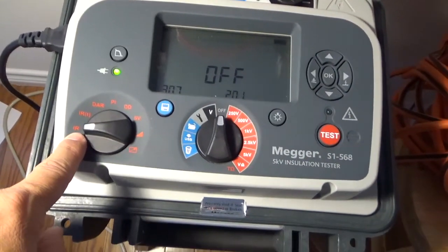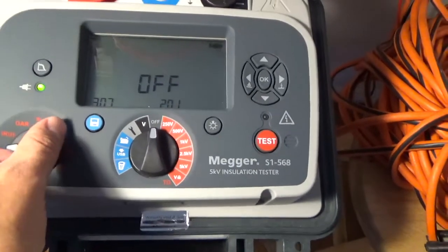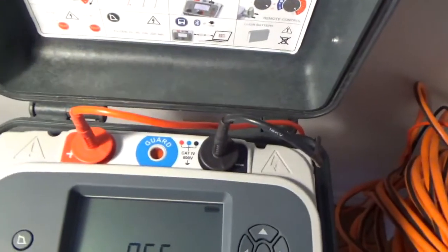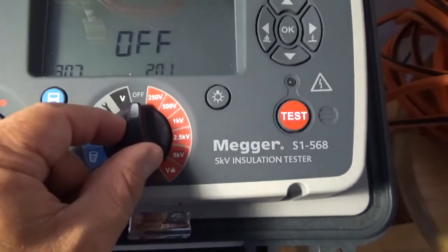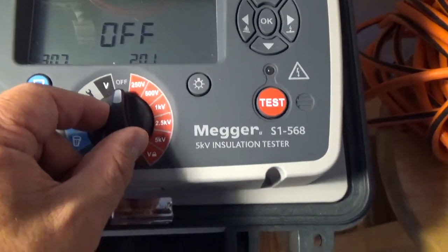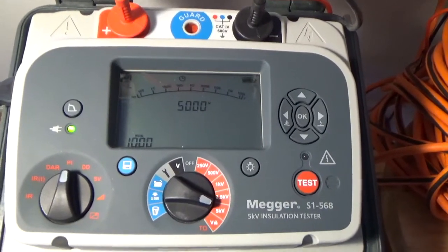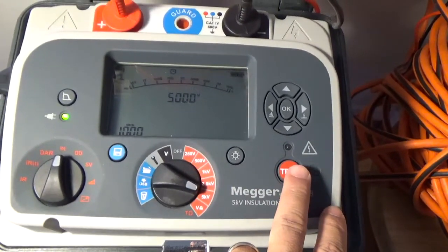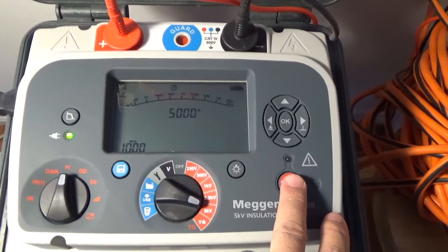There's IR here, insulation resistance, and you want to move it to PI, polarization index. All right, let's move that to PI. We have our setup here on our extension cord insulation. We've stabbed in our leads, and we just need to crank up the voltage on this level here, and then start our polarization index test. Okay, let's just go 5,000 volts. I like to bring instruments to their limit sometimes. All right, I guess we're ready. If you can see the screen, just watch as I start it, and then we'll cut away for waiting and come back. All right, let's start it.